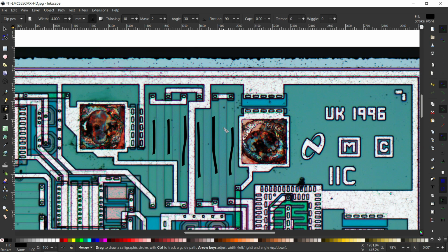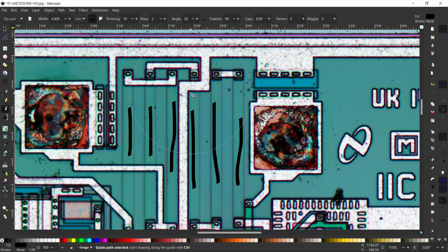So they have divided each resistor into 2.5k, so that overall they can implement two 2.5k resistors as a 5k. Okay, so they are connecting them in series connection in order to derive that 15k resistance. So they have implemented the resistor layout here.